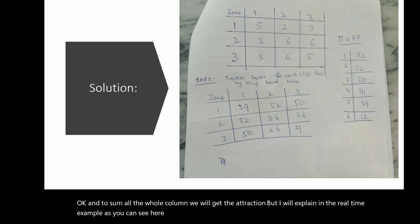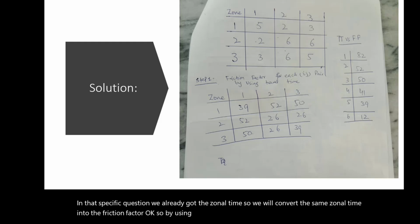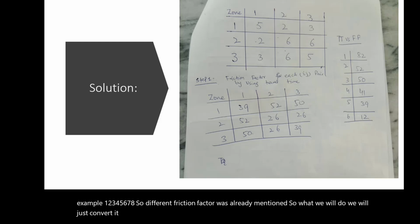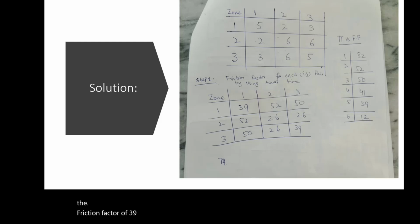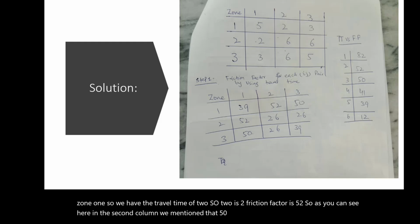As you can see here, what we did. For the very first step, in that specific question, we already got the zonal time. So we will convert the same zonal time into the friction factor. By using the travel time, the friction factors were already mentioned, for example 1, 2, 3, 4, 5, 6, 7, 8. So we will just convert it. For example, for zone 1 to 1, the travel time there was 5, so we have the friction factor of 39. We just put that friction factor over there. Similarly, from zone 2 to zone 1, we have the travel time of 2, so the friction factor is 52. As you can see here in the second column, we mentioned that 52. Similarly, the whole table is generated.